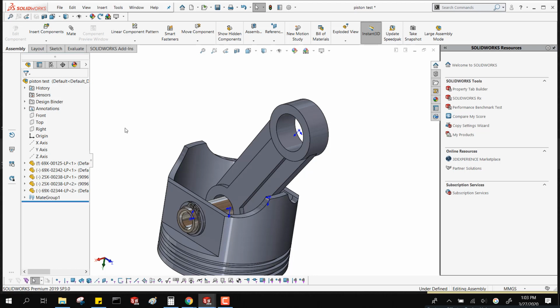So what happens if I go back to the master model and make the change in the top level sketch, which is the advantage of it, of course? Does the sketch trickle down into the floated part properly? I guess we could try that easily enough. I can try that on some of my stuff. Yeah, because it should, because the part's going to rebuild according to the sketch.